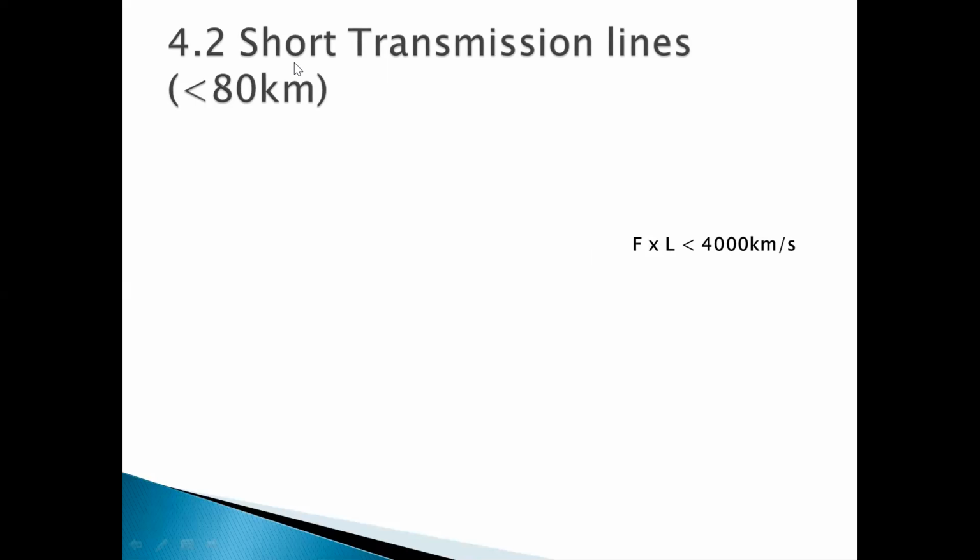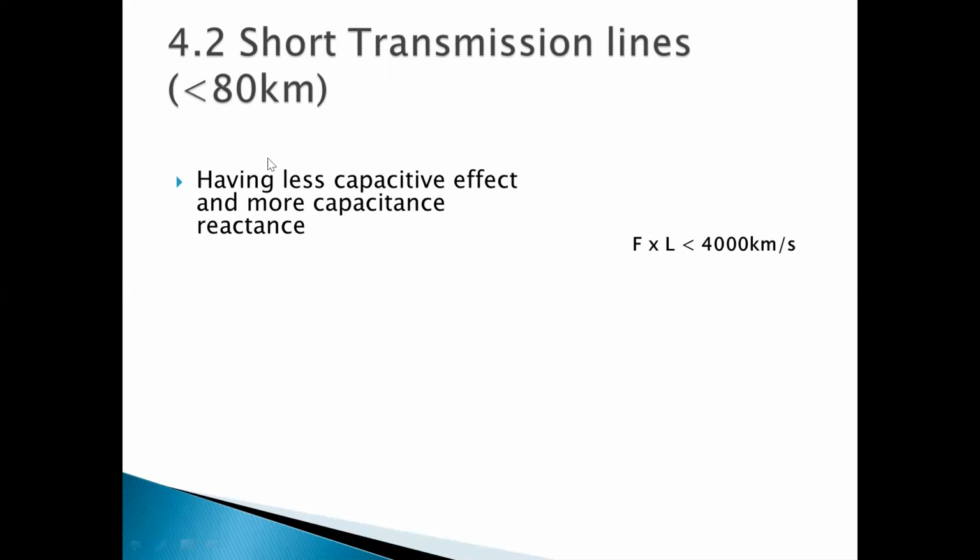That's why when I talk about 80 kilometers or 200 kilometers, I am talking about the frequency of 50 hertz. So in the case of 50 hertz, if the length is less than 80 kilometers, we categorize it as a short transmission line.